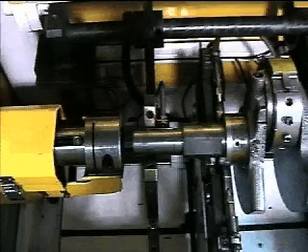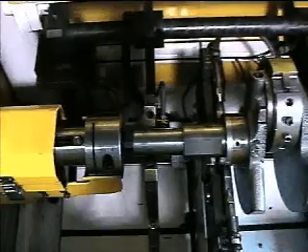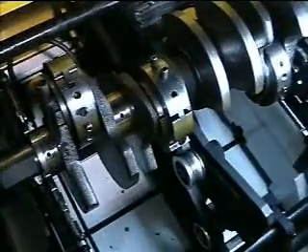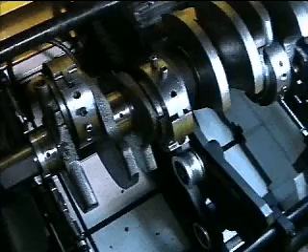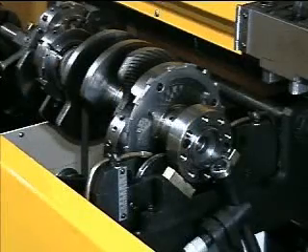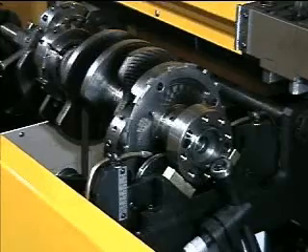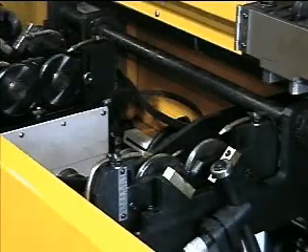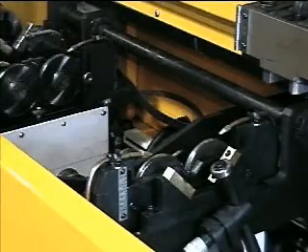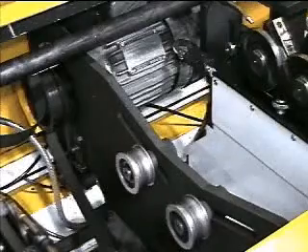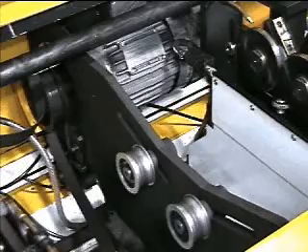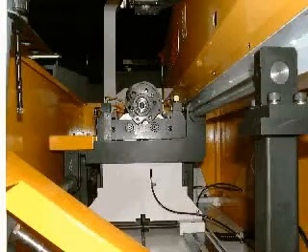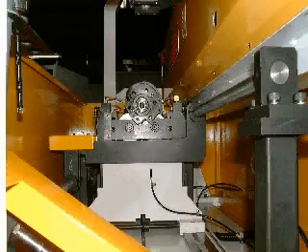This balancer is a non-standard model due to having both an in-drive and belt drive system. The machine cradle's rugged construction can be designed to turn the part on either rollers or V-pads. Adjustable pulleys on the belt drive allow for a variety of part sizes. The supports are mounted on ways and are adjustable for varying part lengths.